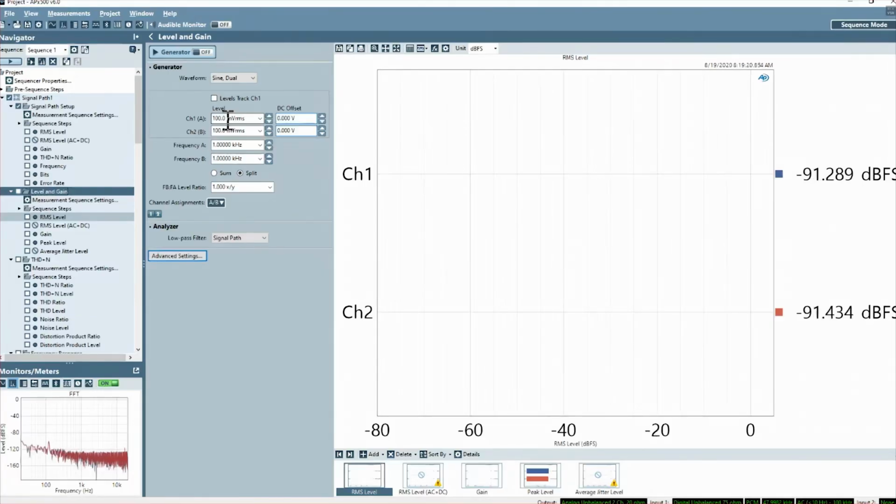The next most successful technique is actually to look at the termination on both ends. Usually you have a discontinuity in termination on the serial interface cables. So it may be worth calculating out and actually adding a resistor so that you have matched impedances on the cable. That would probably be the next most successful place.